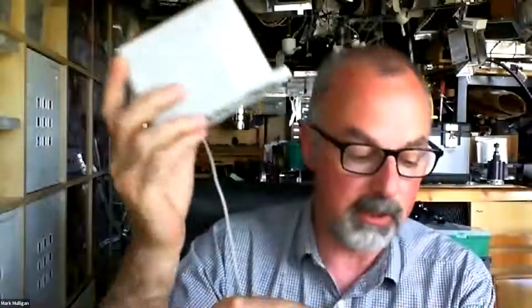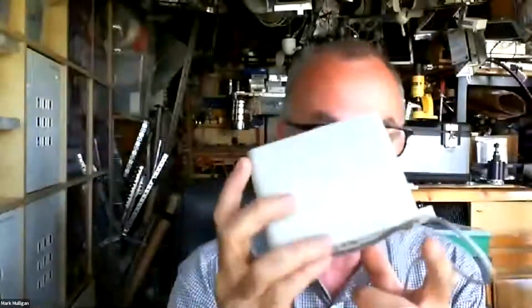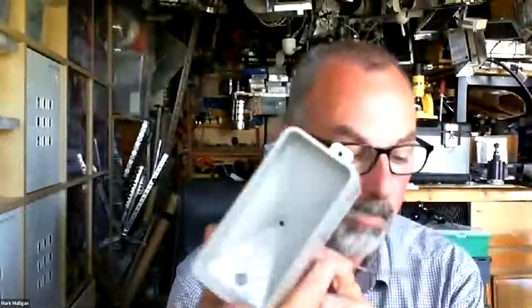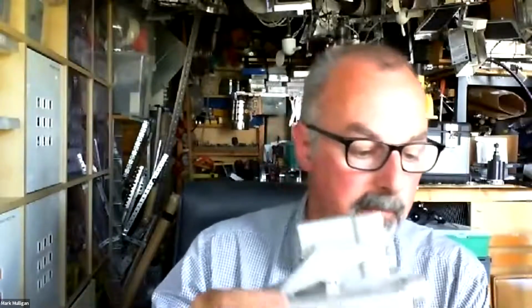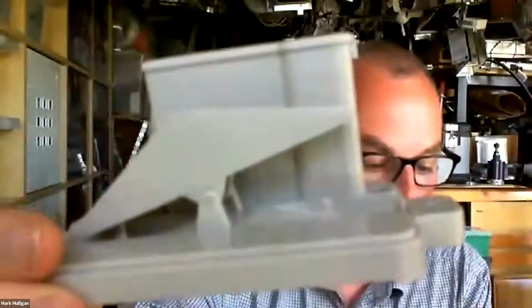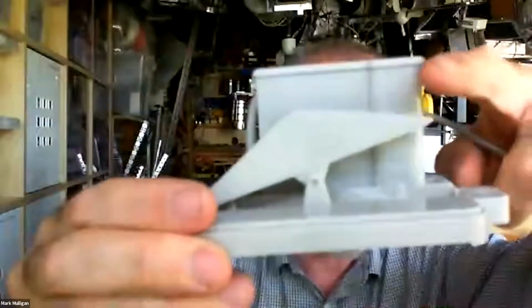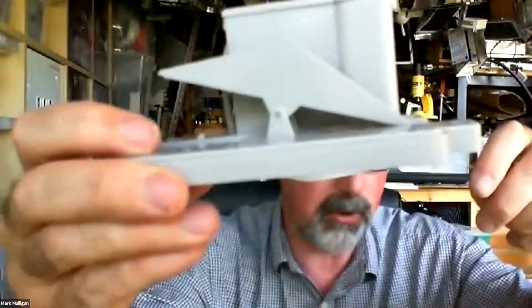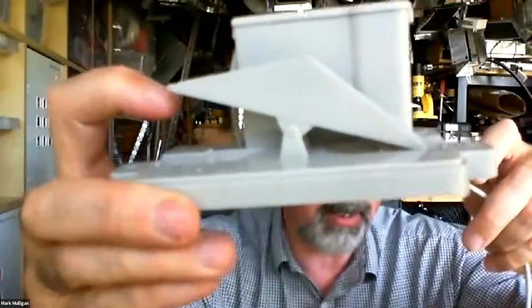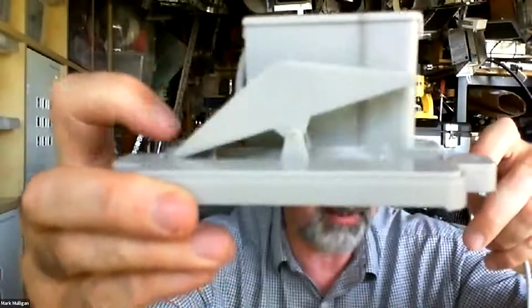I'm showing you a rain gauge. This is a very cheap, again, rain gauge, used to be sold by Maplin Electronics, built in China. It's a tipping bucket rain gauge. It uses a small bucket inside the device that you see here. As water fills one half of that bucket, it then tips, and that makes a count on the microprocessor, and water starts to fill the other half of the bucket, and then it tips again.